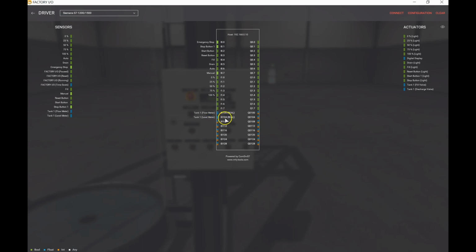Okay, so we have the flow, and more importantly, we're making use of the level meter. So that level meter is going to go to ID 104. You notice that these guys are I believe 32 bits. We're going from ID 100 to ID 104. Okay, so next one we have, let's see, that's all of our inputs, right? So input 1.4 was my last discrete input. Then I had two analog inputs. Beautiful. Okay, over here for my actuators, I have my lights for indicating all of my different levels. So 0 through 100.